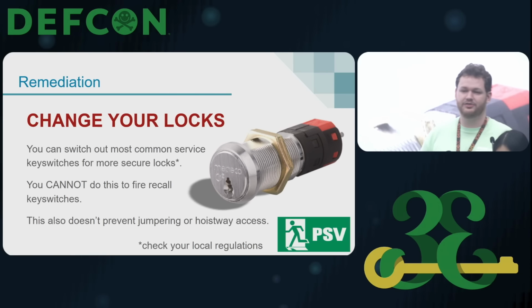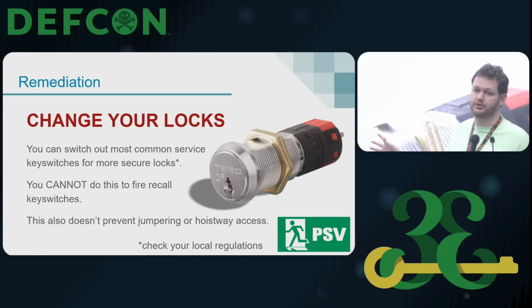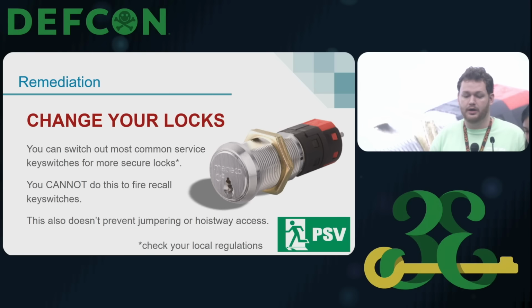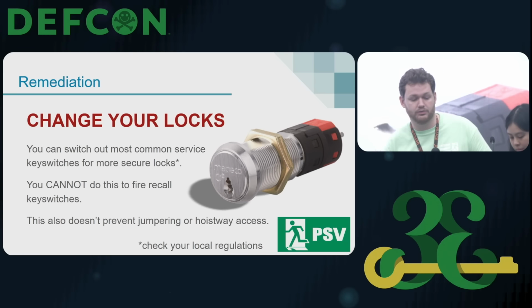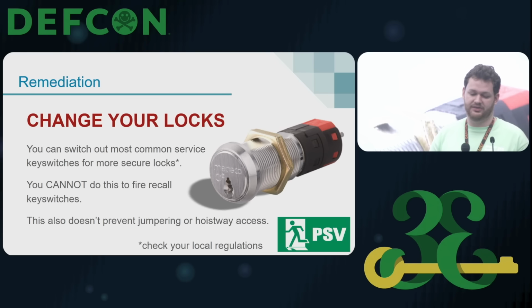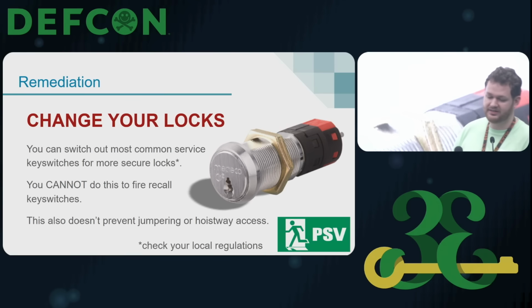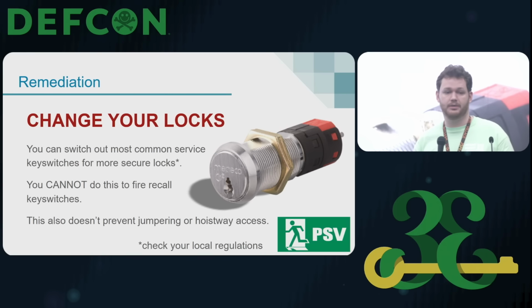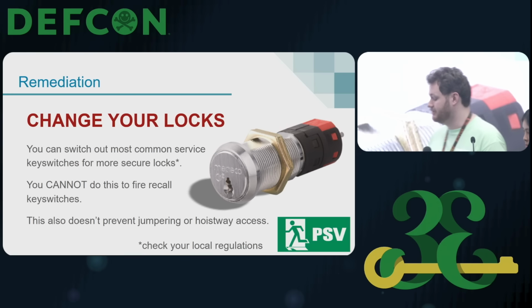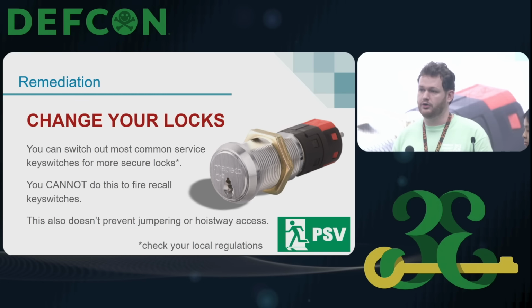So the best remediation for these is to change your locks, so you can switch out most common service locks that will again give you access to the internal mechanics inside of the panel. But you can't do this for fire recall key switches. There are also additional methods that this doesn't prevent, like jumpering and hoistway entry access. But make sure that when you're doing any modifications to your elevator systems that you confer with local regulations in order to make sure that you are not doing anything that would be against fire code or other additional